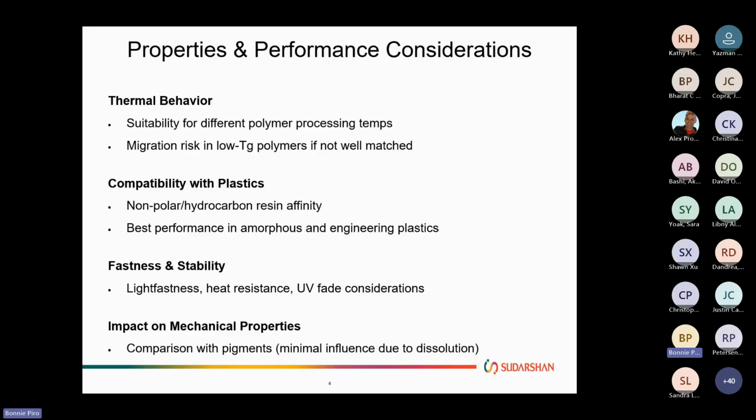If you're using multiple dyes within the color itself, take note that there might be a change in the rate of fade of the dyes. So when you have your initial color, during the fading process it could change color direction based on the rate of fade of that particular dye. Your end color could look different in those intermediate stages.